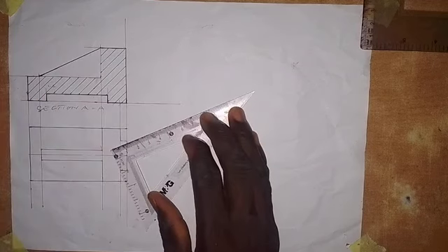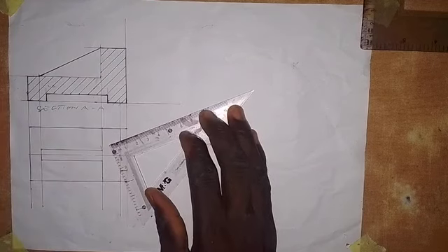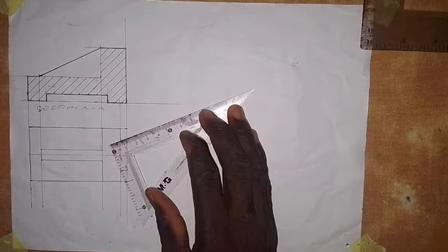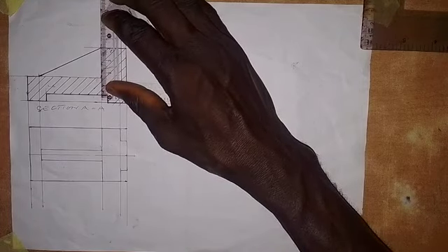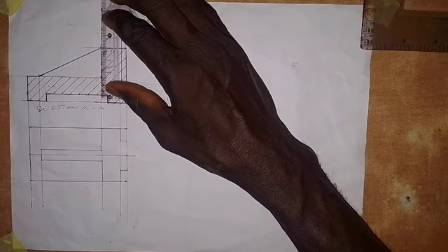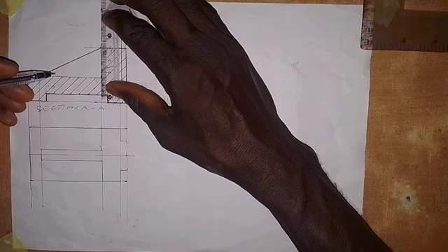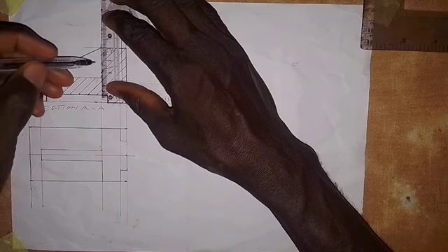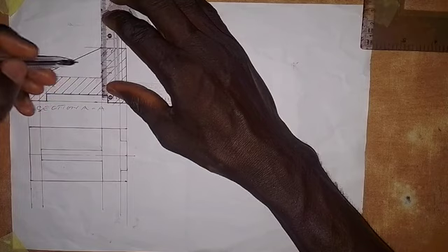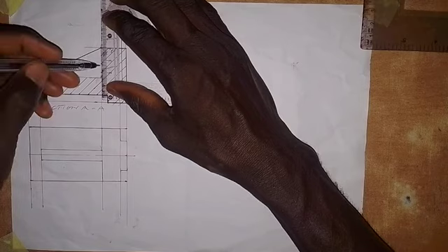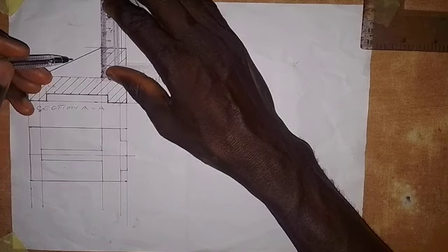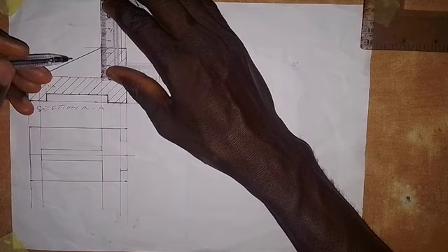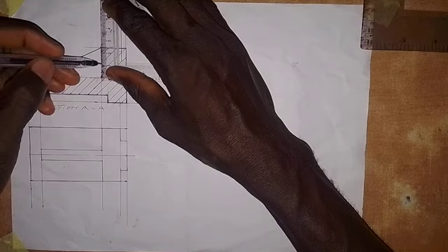So if I divide 55 by 2, or instead of doing that, let's take the distance on the vertical. I think that is the best way to look at it, since where the cutting plane touches this part is not given. So let's take it as 10 millimeters, as I've said before. Let's break it down. The distance from here up is 25 millimeters, so 25 by 2 will give us 12.5. So let's make it 12.5.